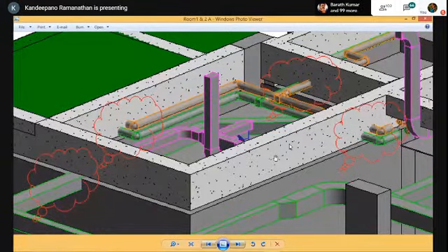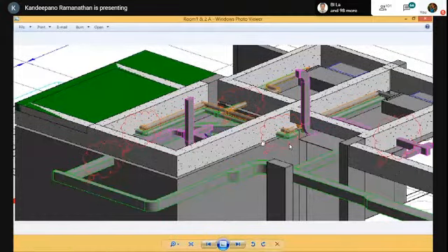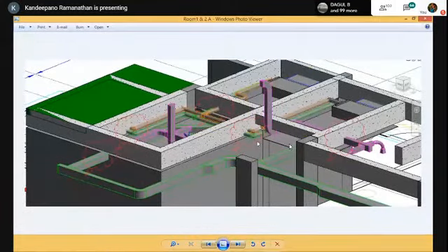This is the toilet portion above the false ceiling. This is the pipeline, and this is the clash. All these clashes are identified to the structural designer, who will give cutouts, or he might reduce the beam height or whatever. Or ultimately, he'll ask us to reroute our piping some other way. So this is what happens. This is the designing aspect of it.